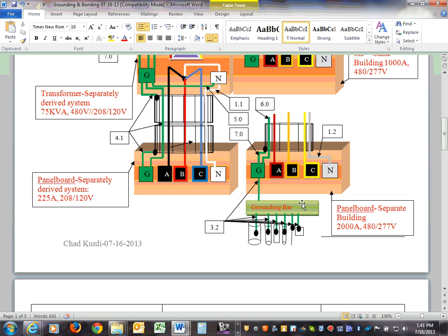For a very large existing building where the water main coming in was at one end of the building, and from the entry point on it was PVC or PEX throughout the rest of the facility, and the service is at the other end, is that considered available? Is it one structure with one service? Multiple services coming to the same structure? You're supposed to bond them together.